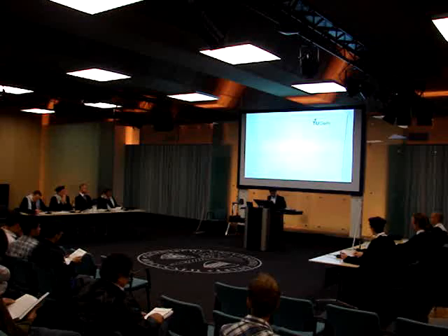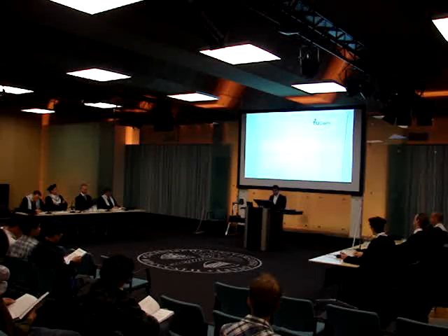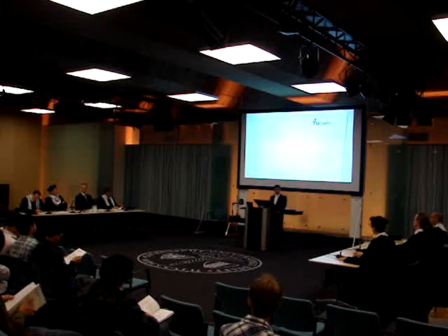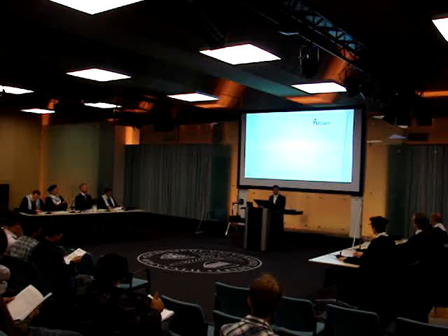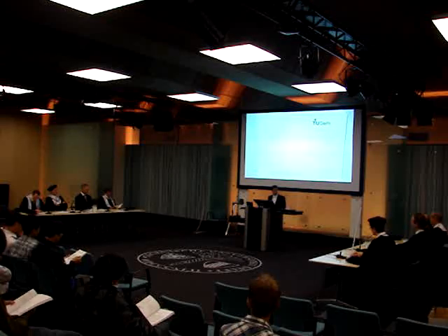Yeah, I used loss of stability of materials as a criterion to detect crack initiation at the macro scale. So at the micro scale, localization is detected, and then I insert a macro crack at the macro scale to regularize the macroscopic boundary value problem.